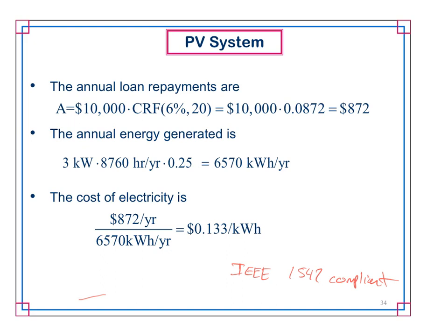You go out there and you start working on the line, and somebody's PV system is cranking out kilowatts, and it's back feeding from that house, going through the breaker panel, up into the transformer that's at 240 volts, stepping it up to 7,200 volts. The line is energized at 7,200 volts. So now the utility company has lost control of the line. Now, that's a little bit of a misnomer, because if your PV system is on the line at 7,200 volts, your neighbor is going to try to take power away and it's going to pull the voltage down in the system, so it probably would trip on overcurrent anyway. But it's not a guarantee of that.